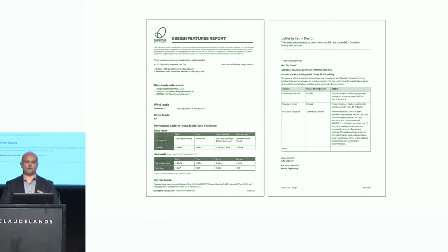It's a good way of keeping it done. If we can be detailing out what our loads are and so on, then it makes it a lot easier to check. If you can be putting it down there, with a picture, then you're likely to get a lot less questions from the checking engineer. The reason being that they can see at a glance what's going on. Are your assumptions right? And if your assumptions look about right, then chances are the rest of your documentation is going to flow through, right?